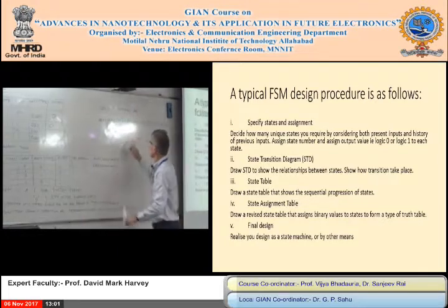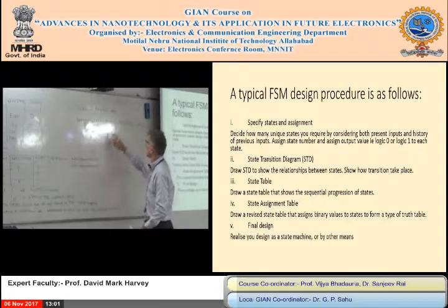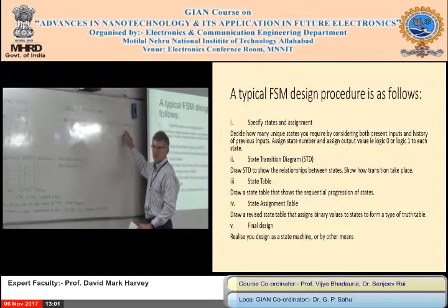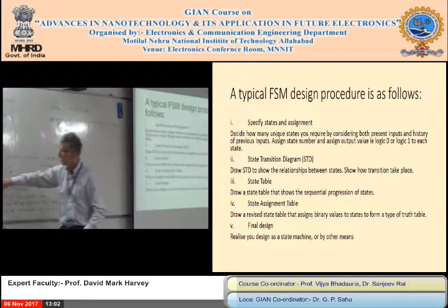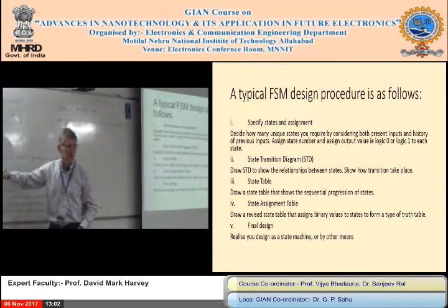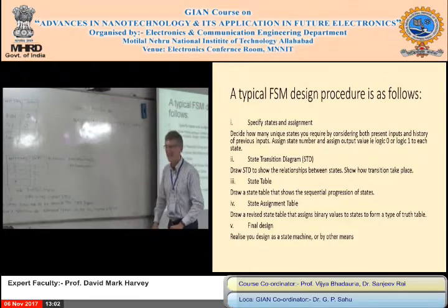So this is the equation. Next state, which is what we're trying to get there, is present state exclusive OR with the input, and the other one, you see this one just follows the present state. No gating required. Isn't that great?